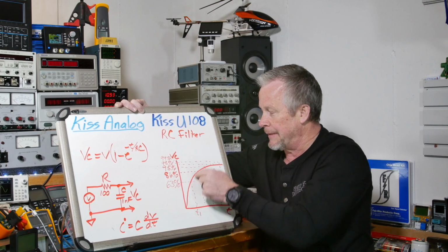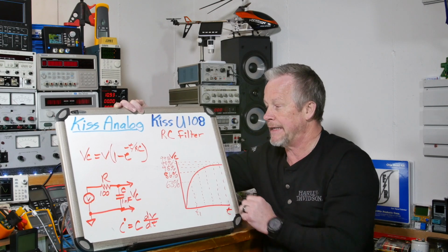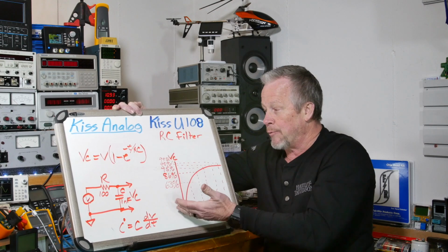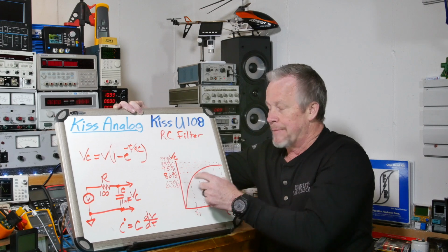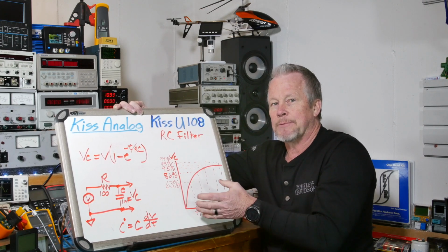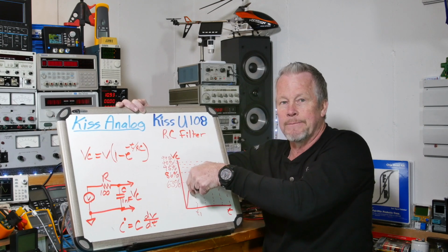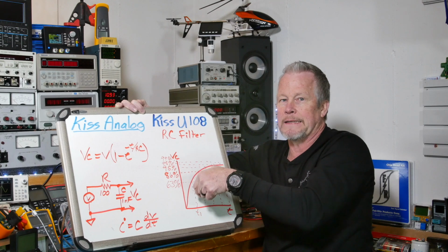Like your rise time might be like this, and then it's skewed because it takes forever to get that last 10%. And you can kind of see why, because if you take off 10% here, 10% up here, that's 80% left over. So 80% of your wave shape is really what you're using for rise time.